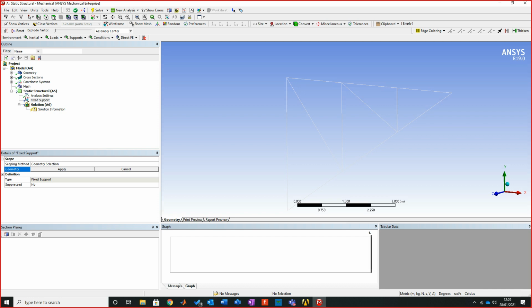Really, it's a roller, so I do really need to apply that, but for this, I know the type of result we're going to get. The thing is, at the moment, if you try to move across, you kind of look and go, it's not doing anything. It's just not working. Look over here. We've got tools we can use to click onto, ways of attaching to. We've got edges, so if I click on edges for example, I could choose the entire edge to fix it. It's not that. I'm going to click on vertex,